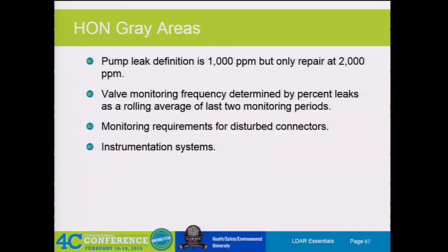Some facilities will take it, some won't. I've been at facilities where valves of 1/2 inch or smaller don't have to be monitored, and connectors of 3/4 of an inch or smaller are exempt as long as they're part of an instrumentation system. So try to be consistent if you ever take that exemption. I was at one place that did take the exemption on analyzer houses, but every transmitter block in the field was tagged and monitored. Very inconsistent in how they were going about that process.